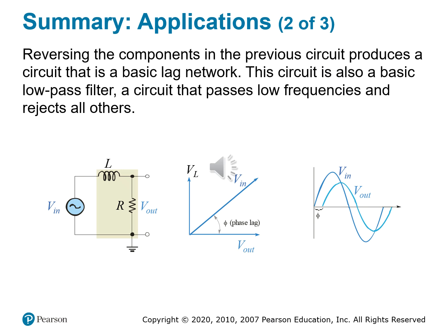And here's how this version works. The configuration stays the same. An AC input V sub in, right? You have a series RL circuit, but now instead of taking the output across the inductor, we take it across the resistor. And this changes the whole function of the circuit.